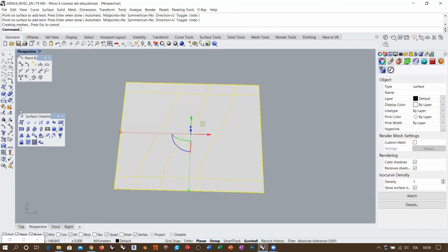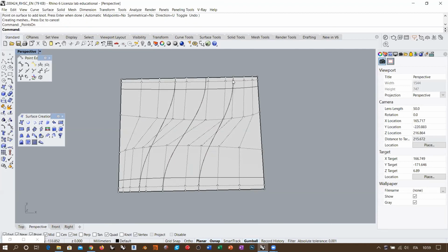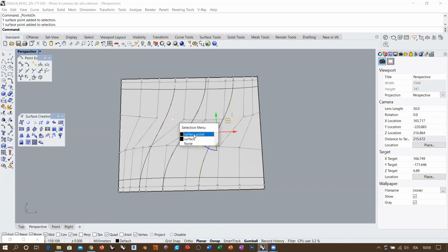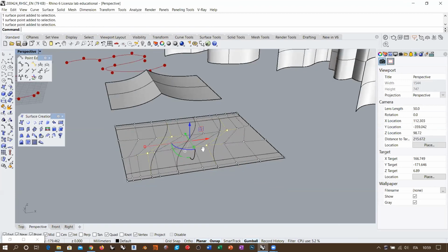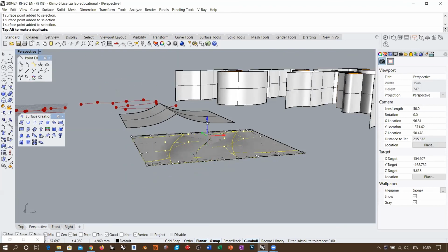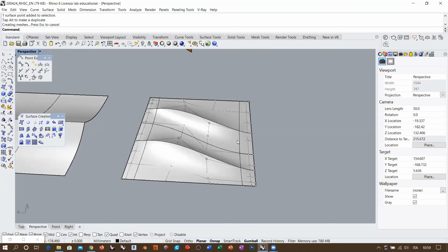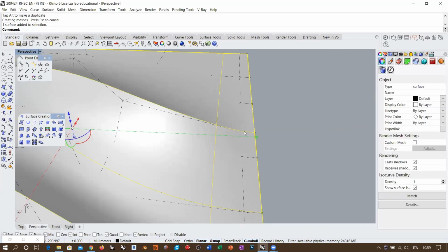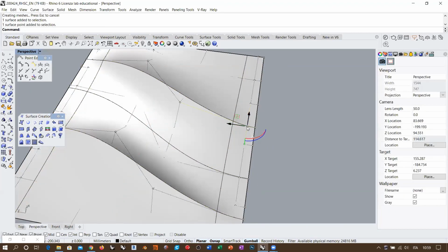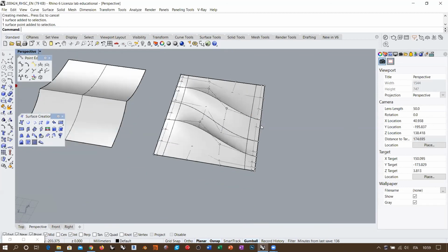So when I activate the control points, I can, for example, take the crease point with the knot, the kink point, sorry, which are these two here, and also eventually these two on the other side of the surface, and increase their height. I am basically concentrating the crease in the inner part. And as this kink point is still lying on the floor, there is horizontal tangency, so the crease disappears more gently when it reaches the edge.